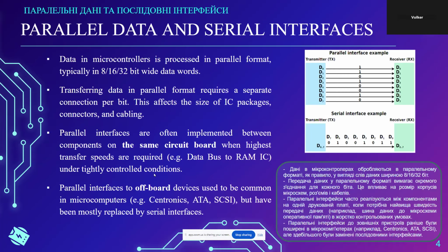Under tightly controlled conditions, that of course means the length, because the transfer speeds are so high that the length of the traces on the circuit board has to be equal, because it has to be guaranteed that the signals on every bus line arrive at the targeted device at the same time. And the speeds that we're talking about are picoseconds.